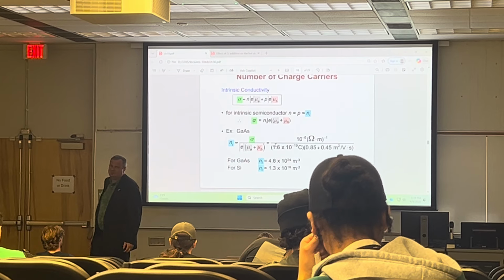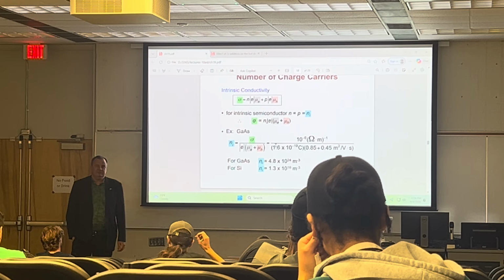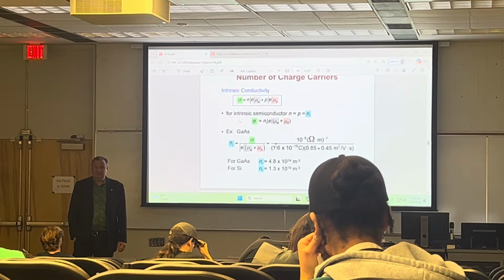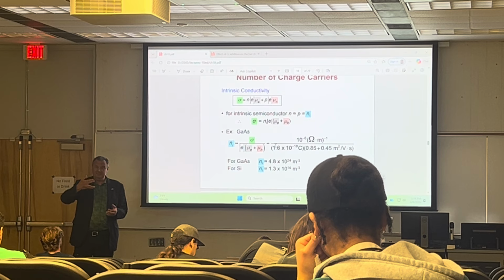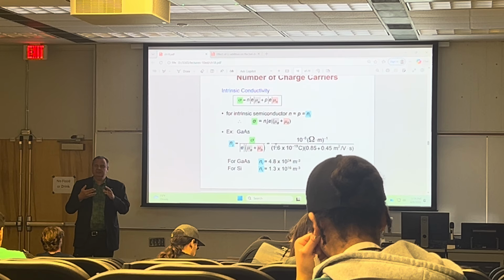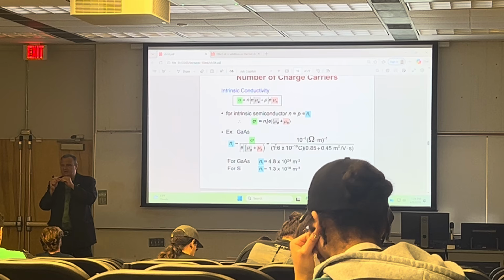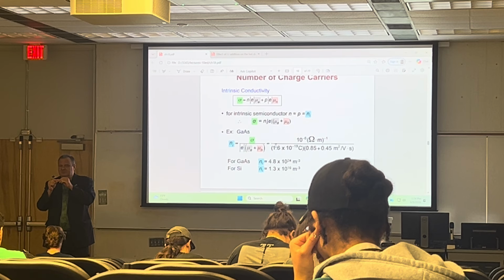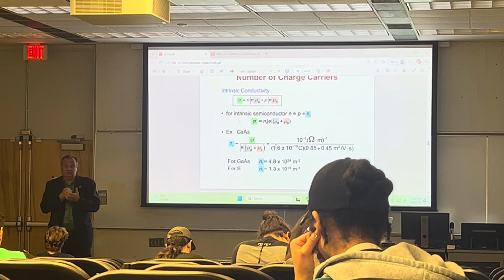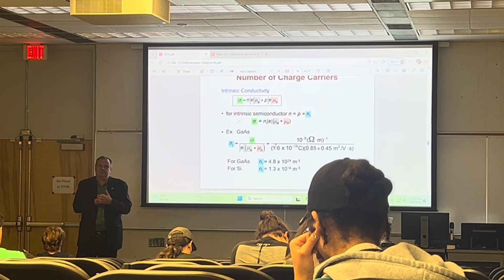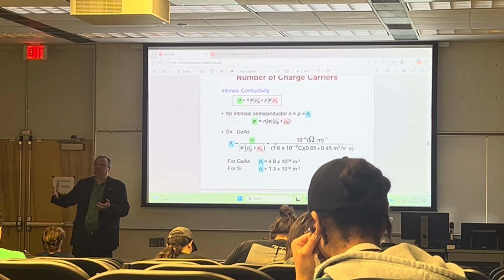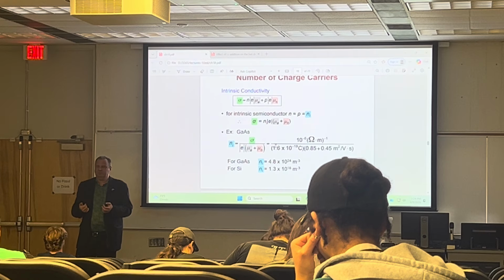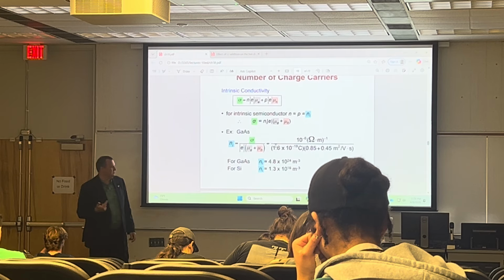Next semester, I'm scheduled to teach fracture mechanics. And we discussed that a little bit when we talked about fracture. You can either measure the crack length, if you can, but if you cannot, like in this tiny little thing, 2 by 2 millimeters, you have to test it mechanically to crush it. And then you would develop Weibull statistics. At which strain, at which level of the stress and force it breaks. And then you back calculate the stress, and then you try and get crack length, and you're trying to reduce it somehow.